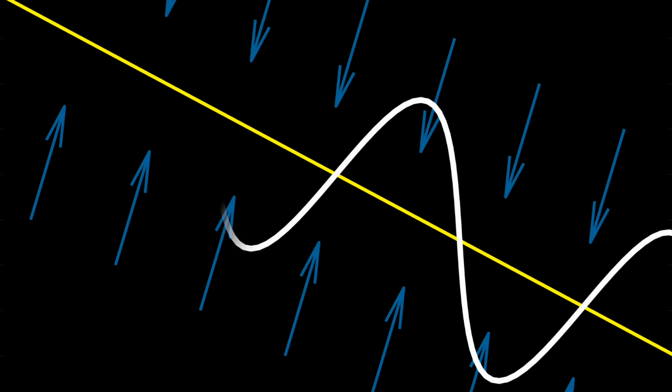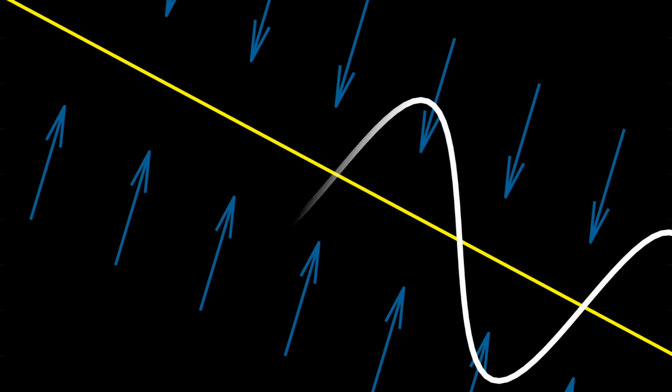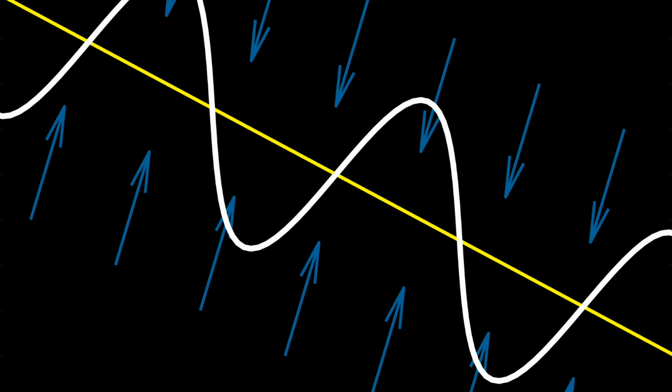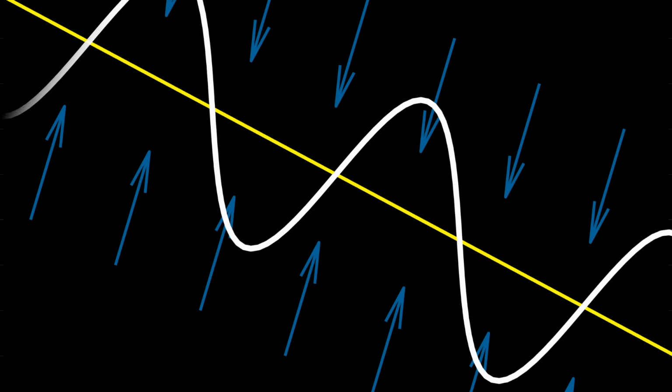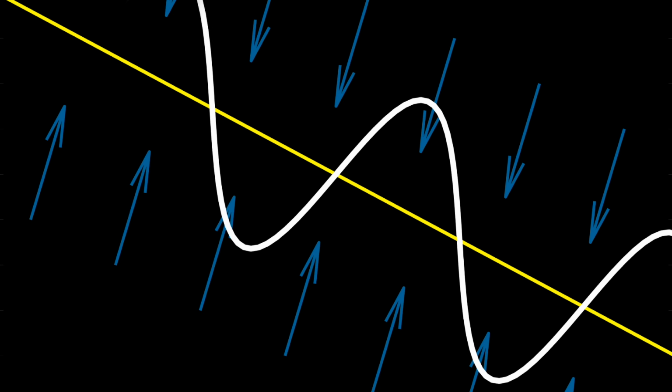However, the downside of this switching high gain approach is that we introduce chattering into the system. Chattering is when the system states bounce back and forth on either side of the switching line, and it occurs because of the finite time between switching. With high gain, this means that for one time step, the system is really driving the state hard in one direction, which jumps it over the line. And then, the very next time step, it wants to drive it hard in the other direction. And delay in the system only exacerbates this chattering.